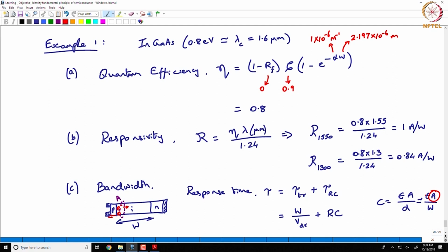So, what you would find is, if you look at commercial photodiodes, you have these relatively run of the mill, commonly available photodiodes, which are large area, 3 millimeter, 5 millimeter active region. And when you look at the response time for that, that will be in the order of microseconds.